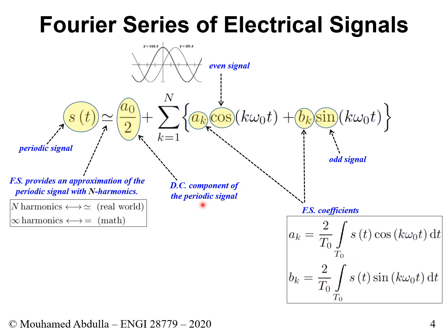And you simply take the periodic signal here, you multiply it by cosine, this thing here, with respect to dt, and then you integrate with respect to t, and you find the result. Now, don't forget, you're not integrating forever. You're only integrating over some window of T0. You choose whichever window of T0 you want to consider. All windows of T0 of your periodic signal would work. So choose something that will make your analysis easy.